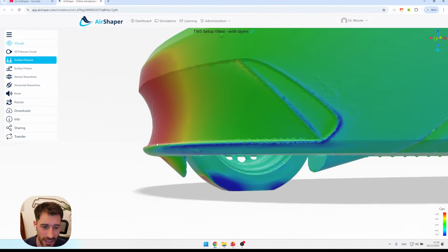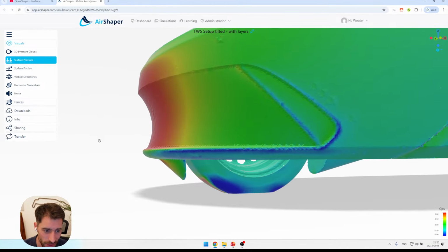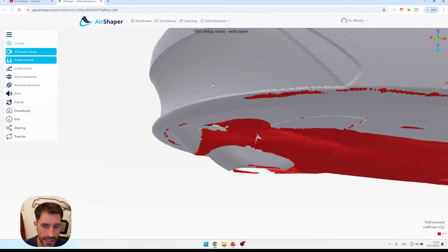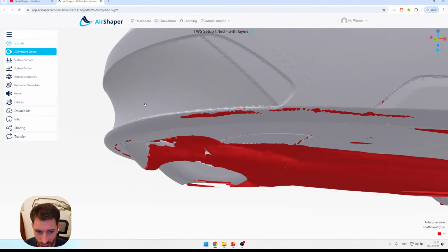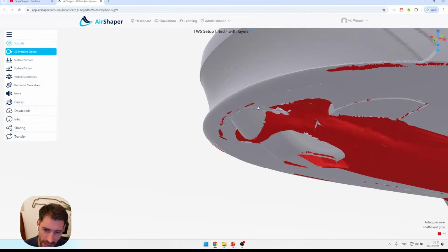In this case, usually if it would stick out, you would have flow separation around the sharp edge. This one already had a nice round here, which is good. We have attached flow at the bottom. It's only at the sides here, around this sharp edge, as soon as the flow tumbles around this one, that we saw some flow separation, small challenges here.